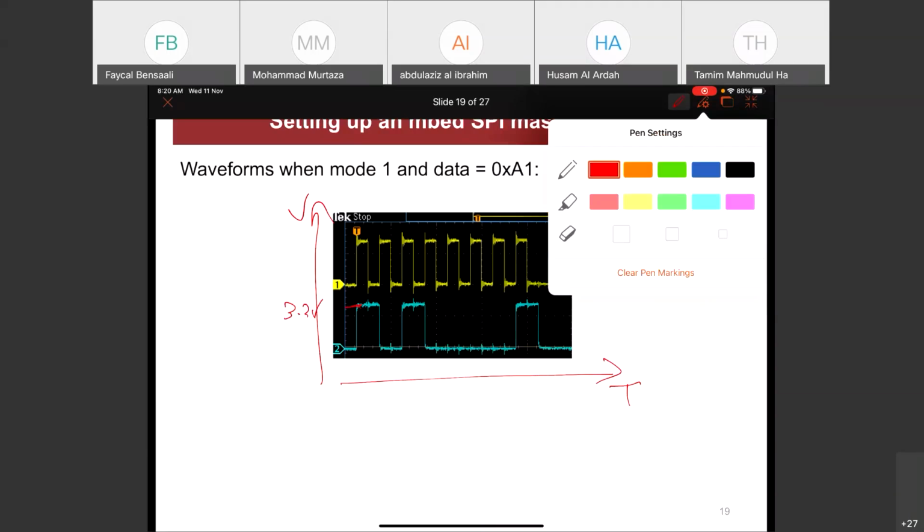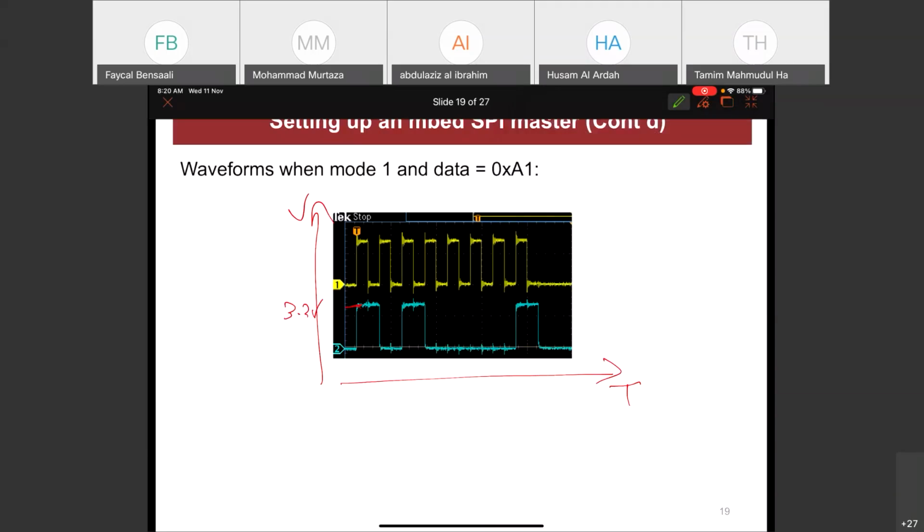So remember we said it is rising edge. So we are working with rising edges and in phase. So do you see this is 1, 0, 1, 0, 0, 0, 0, 1. So those are the bits that have been transmitted. And of course, this one is the first, right? Because we start from 0. This is time. We start from 0. So this is the first bit that was transmitted. This is the second bit, and so on. This was the last bit transmitted.